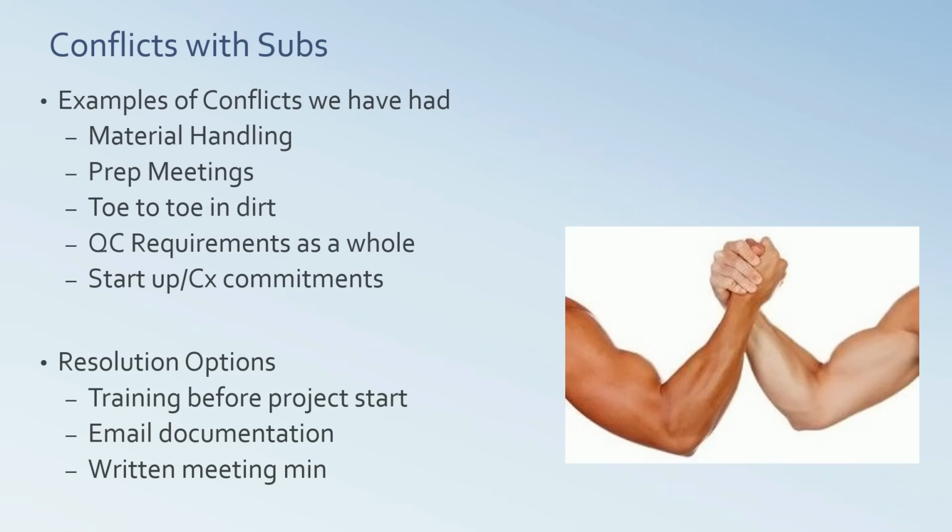A lot of the feds want material on dunnage and covered. This is a very sore subject, especially for the fitters and the utility contractors, because they'll bring pipe out and they want the pipe on dunnage and they want the pipe covered, but it's pipe that's going to go into the dirt, and they don't see the need for that extra cost on their side. If that is a requirement in the contract, that's a requirement and they've got to do it.